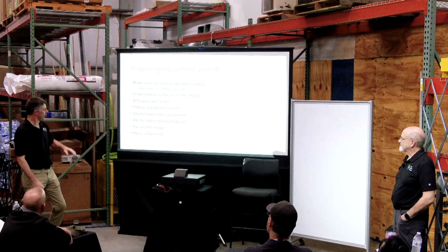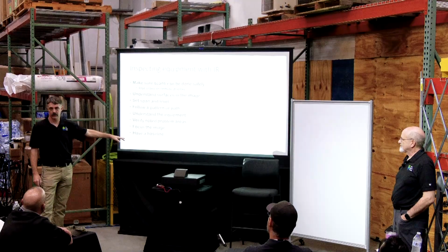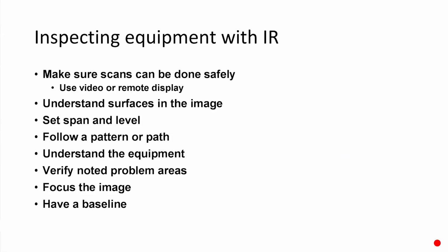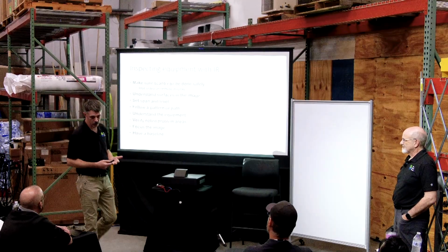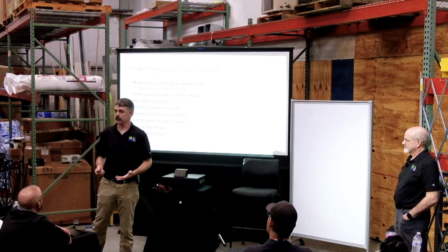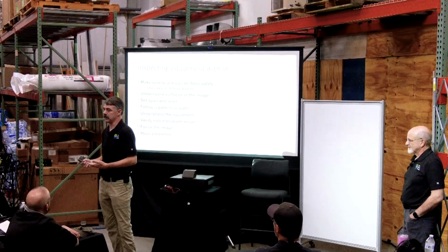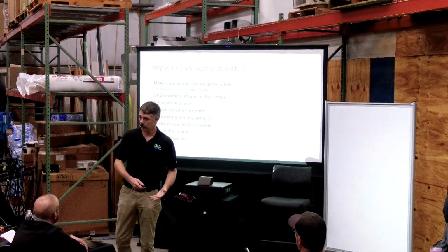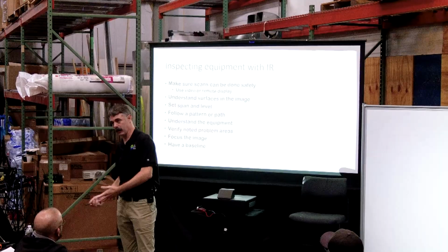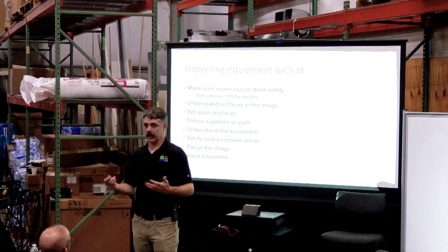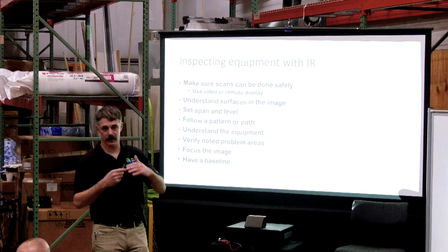Now, you want to have that baseline. Again, that goes back to knowing that equipment. If you're looking at a piece of equipment and troubleshooting it, you need to know the sequence of operations, how it's supposed to work, before you can tell what's not working. That's your baseline.